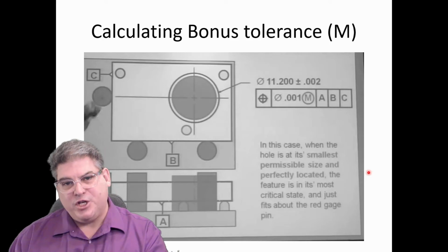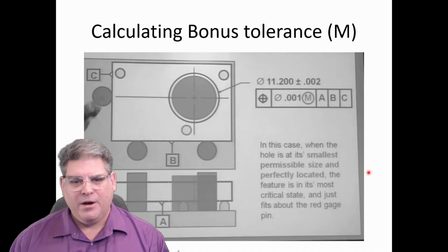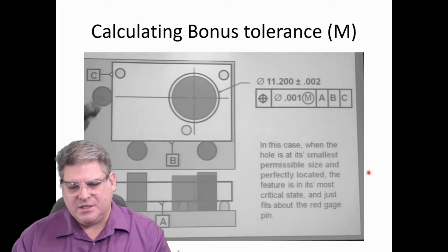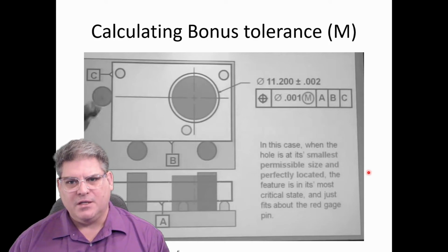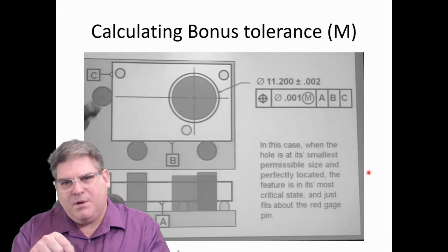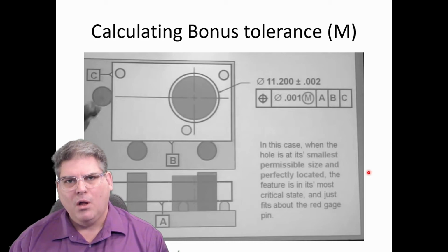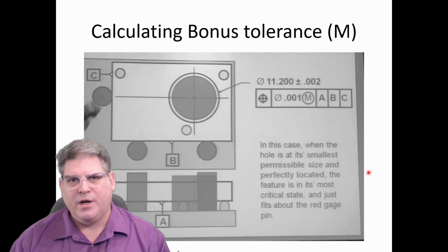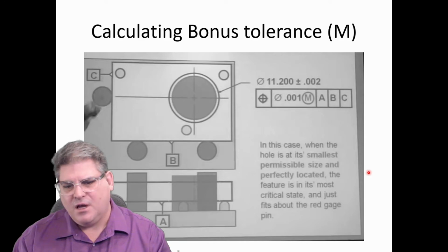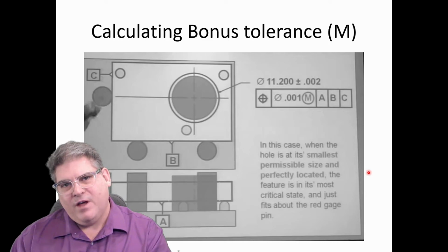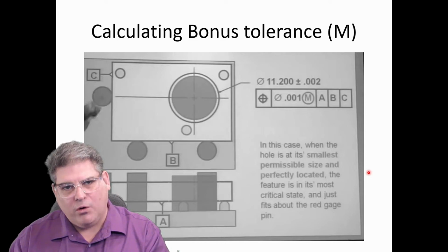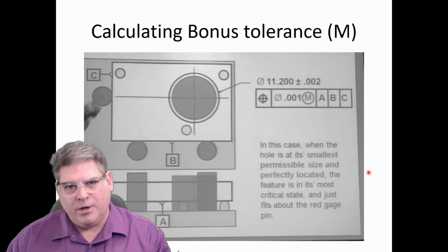Obviously, I don't want my switch falling through the hole, but the minimum clearance, let's argue, is 19 millimeters, but the flange on the top of the switch is 22 millimeters. So I have 3 millimeters of land, but I don't want to be able to see the edge of the hole. So I would work it out, and I would say that my tolerance goes from 19.5 to 20 millimeters in the hole, and then position the hole so that it would line up regardless.